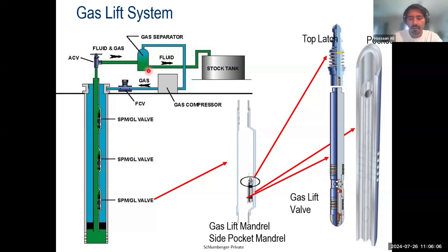Whenever we are doing the well testing and we determine that the solid production is too high, that makes gas lift one of the primary contenders of the artificial lift system rather than a secondary one, just because other methods of artificial lift are not very good in terms of solids handling. Especially ESPs are very terrible in terms of solid handling. Progressive cavity pumps are slightly better, but gas lift systems are one of the best for solid handling. But solid handling does not have anything to do with the wellbore production, wellbore integrity, formation integrity or formation production. They are just byproducts which need to be handled on the surface.